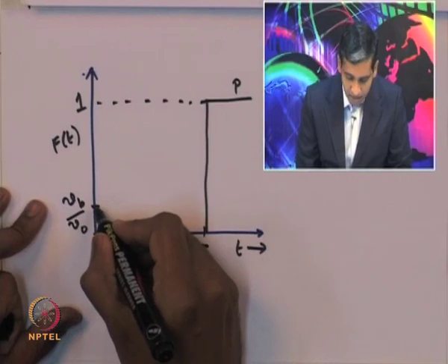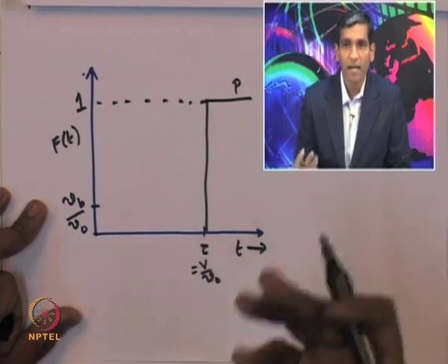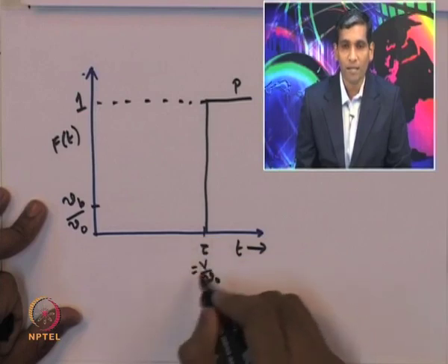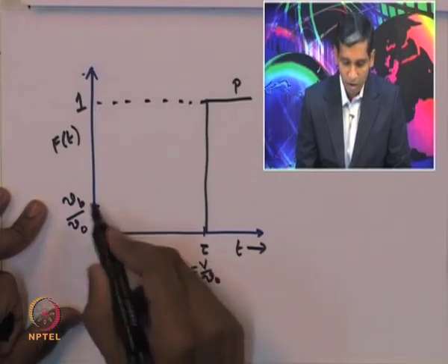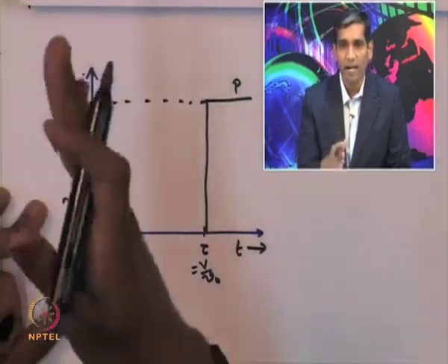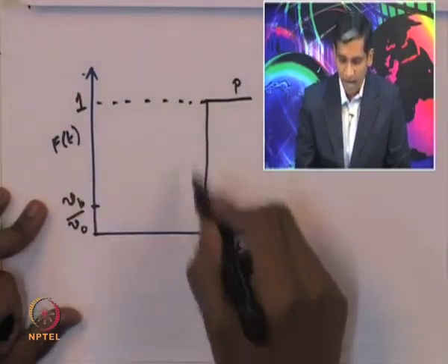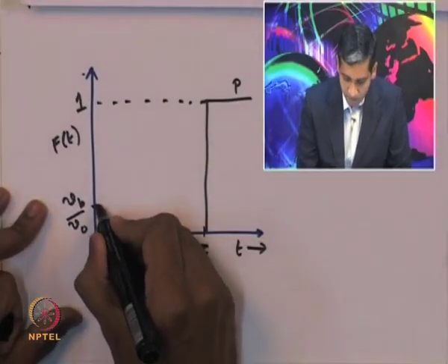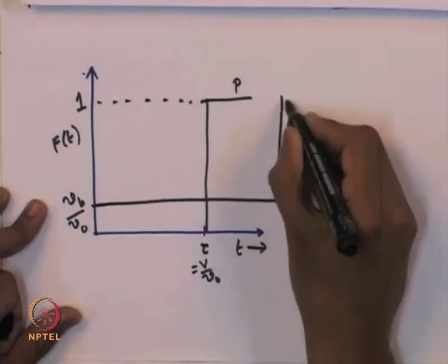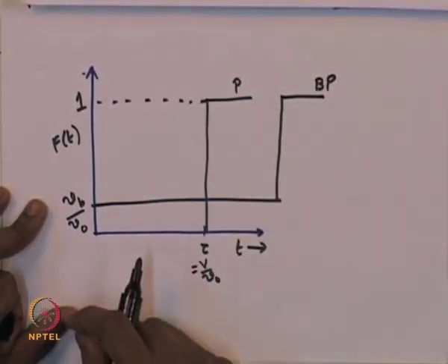Because the space time is now larger than the space time of the reactor under perfect operation, or if there was no bypass, the fluid stream that enters the reactor is now going to take longer time to leave the reactor as compared with the perfect operation. Therefore, the F curve will look like this if there is a bypass inside the reactor.